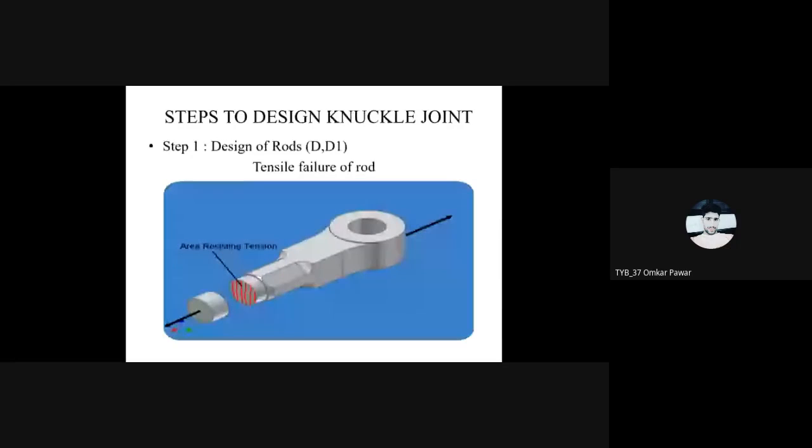Now, in case of ductile material, as we have already seen, the rod is not going to break into two pieces. But if the stress goes beyond the SYT, that is the yield strength, then permanent deformation may occur in that rod, and that can be considered a failure of the rod, though it is physically not converted into two parts. So when the elongation starts beyond the elastic limit, we can also consider that a failure, and hence we are going to consider that as a limit for the induced stresses in that rod.